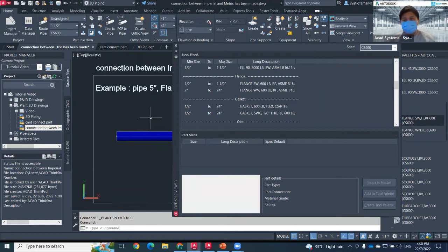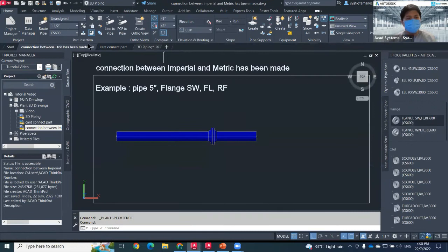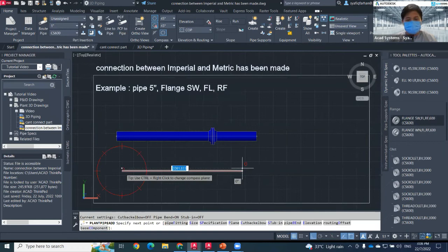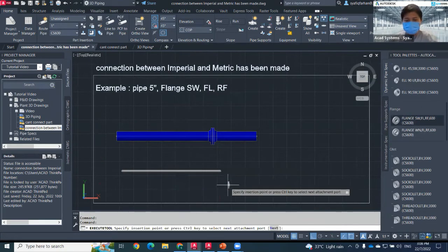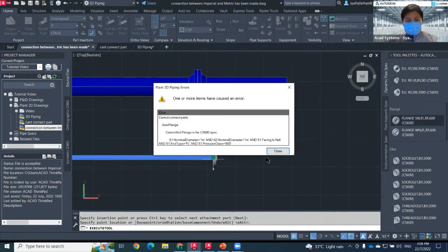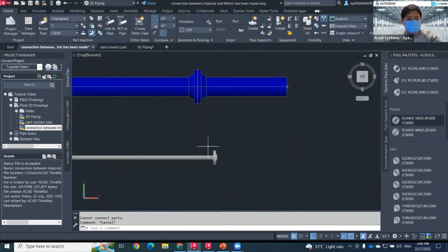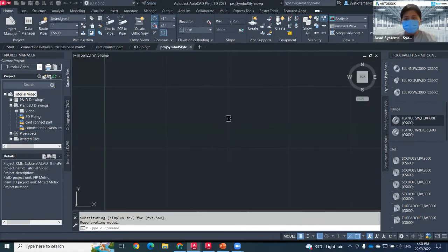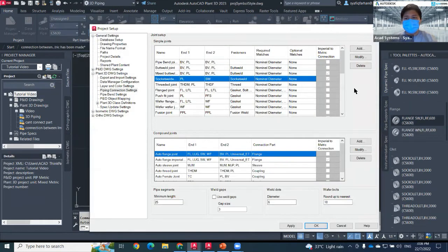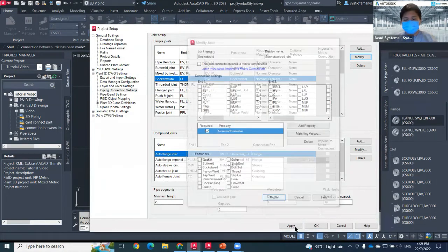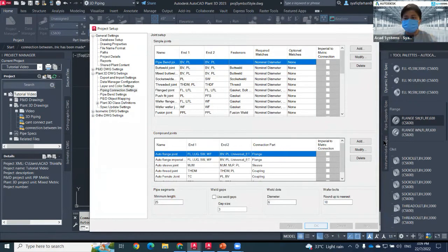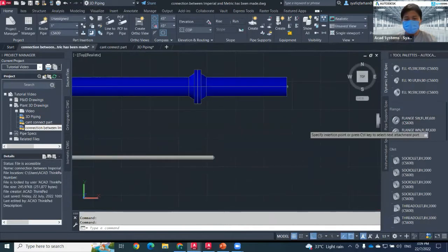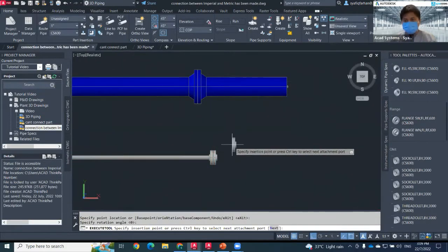That will be the reason. If I try to create ½ inch pipe or 1" pipe, there should be no problem. Over here, I change to 1", create pipe, just the same. Try to insert the flange. Because I already changed the unit, imperial metric, let's untick it back. Socket weld, modify, untick here. From here, if I click and done, problem solved.